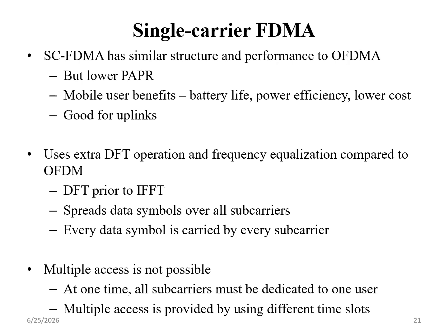Mobile users benefit in battery life, power efficiency as well as lower cost. Why? Because with low power consumption, obviously the battery life will increase, power efficiency will increase, and cost will be lower. It is good for uplink, so SC-FDMA will be used for uplink communication. It uses an extra DFT operation and frequency equalization compared to OFDM.